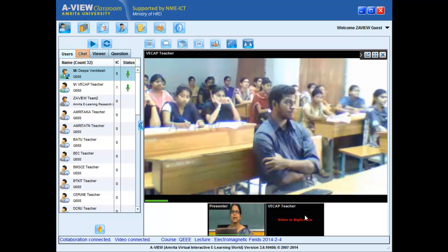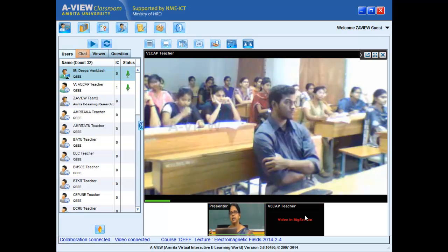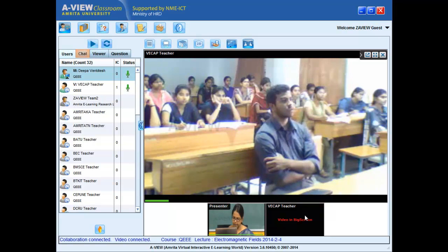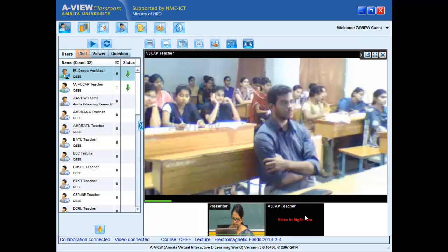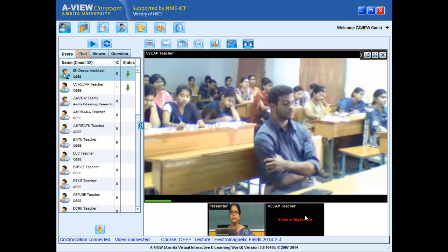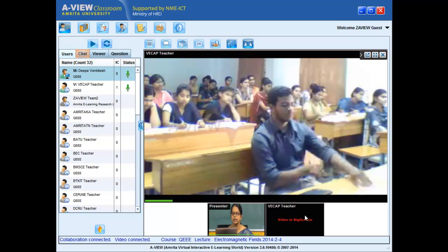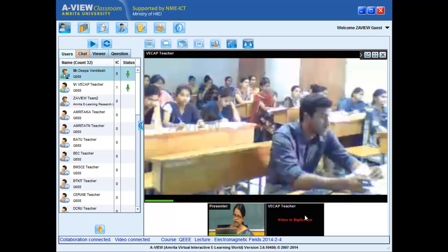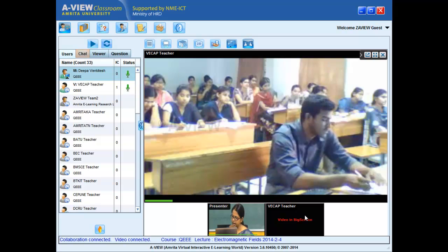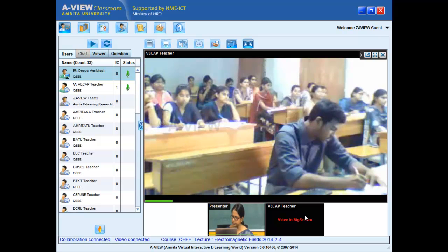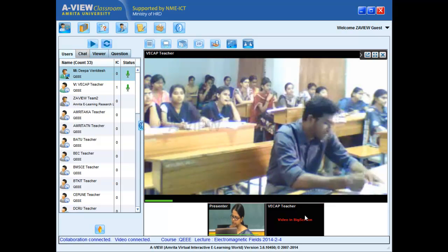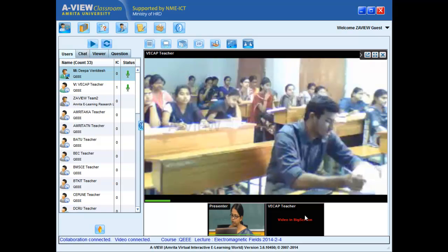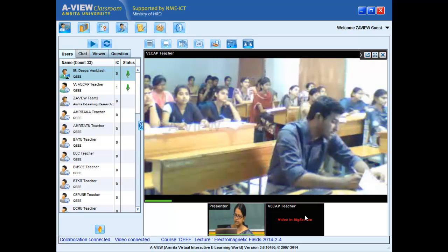You apply all your sign convention and follow whatever, current entering as positive. I mean, be consistent with the sign convention that you use and write down this equation. The current entering is I(z,t). Let me put current entering as plus. Current leaving is, you have current leaving through this, and if I have a capacitor, this is the capacitance C delta Z. I want to know what is the current through this. I know what is the voltage at this point.